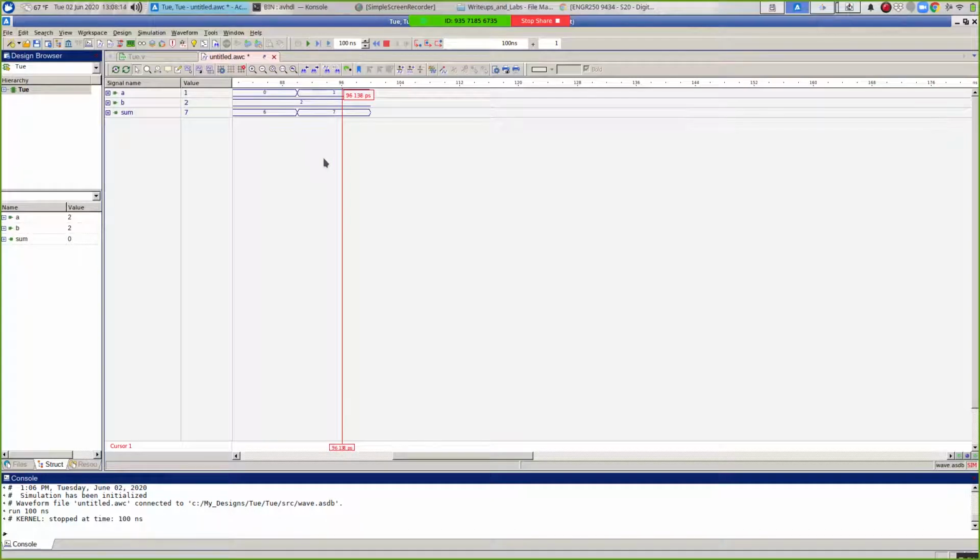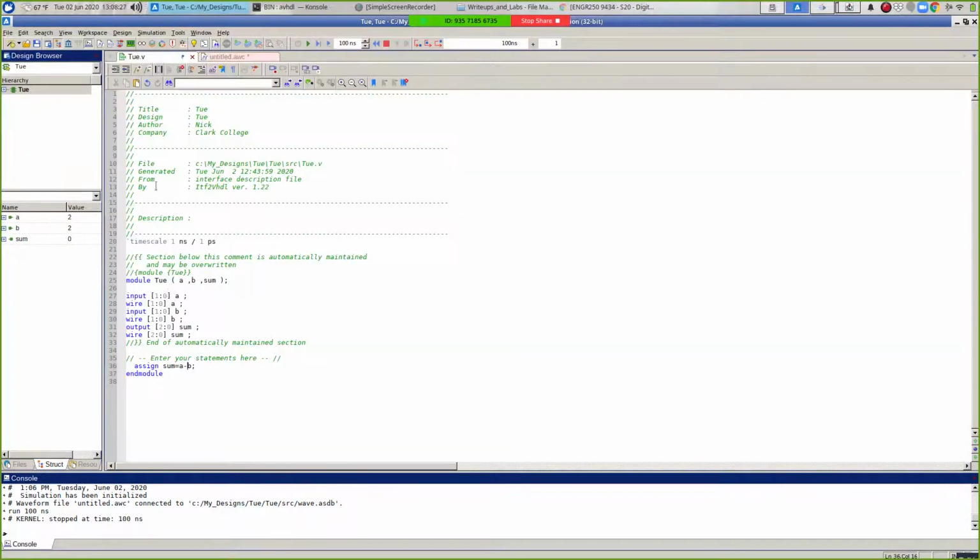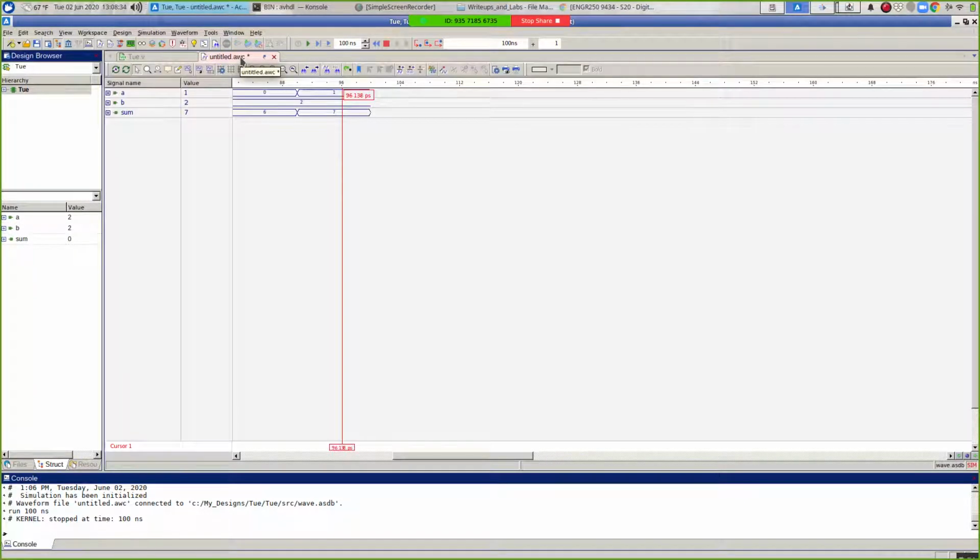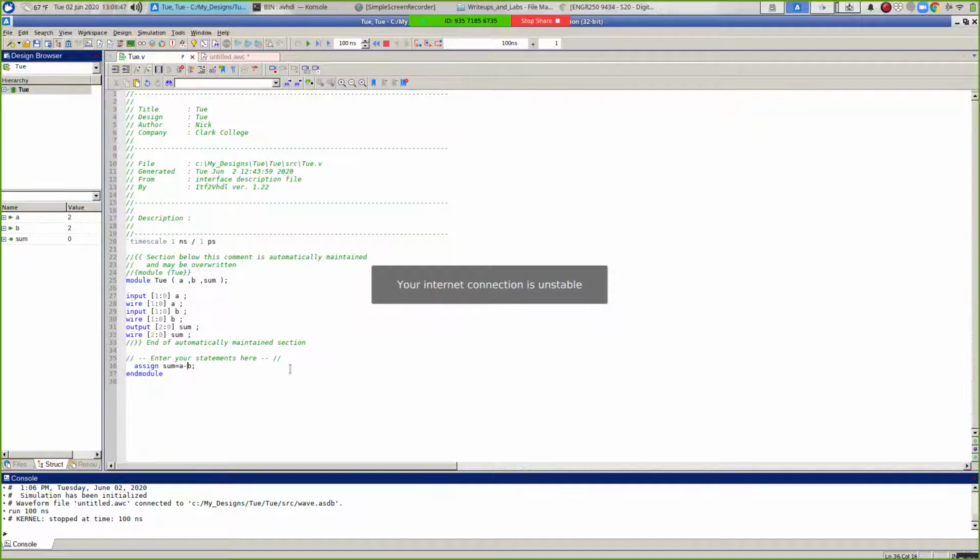So this is a subtractor. It's using 2's complement, it's using bit-by-bit addition, it's doing all the stuff that we've been doing this whole course. But we built a circuit to do this with one line of Verilog code. Assign sum equals a minus b. This is why Verilog is the way that silicon is done today. We don't use protoboards, we don't use K-maps, we write Verilog code. And with a few lines of code, you can describe a circuit that does all kinds of amazing things.